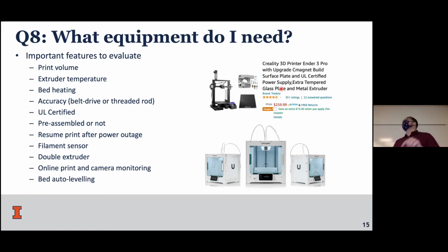Some others have a filament sensor. So if you're printing and your printer is running out of filament, for example, the brain here, I got a spool that was already used, and close to the end, I ran out of filament. It's kind of cool because we can see inside. But if it was a professional print, then I would have to throw it away because I ran out of filament. These printers do not have that feature, but some printers have a sensor. And once your filament is running out, it pauses, and then you feed another filament.